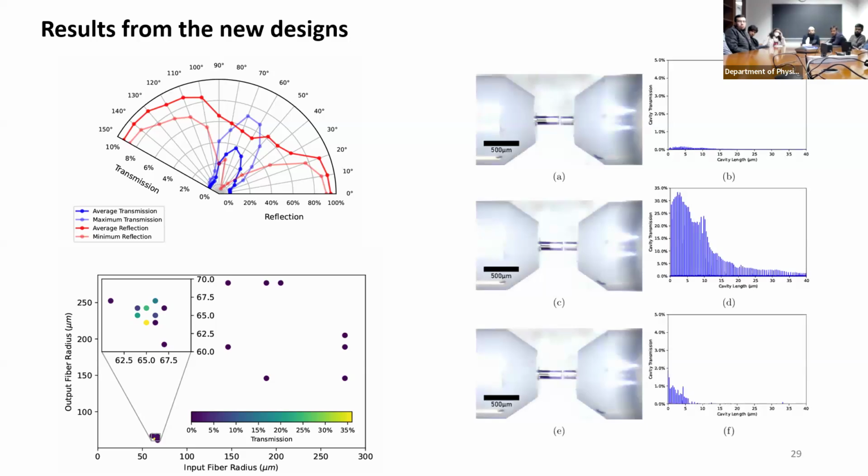And this new design that I mentioned with the bendable mount, I also did the proof of concept of this. Well, it's very hard to see the difference because the change in the transverse displacement is very, very low. It's up to a few microns, but you can see the difference in the transmission. This scale is actually 35%, and this thing is 5%. So the transmission goes from less than 1% to up to 30% with just a few microns of displacement of your fiber. So the idea was to get a mount, try to see what are the different solutions to getting a better transmission, and whether we can make it open access and still have good transmission, good performance, and good stability.